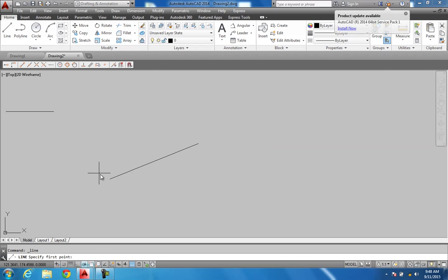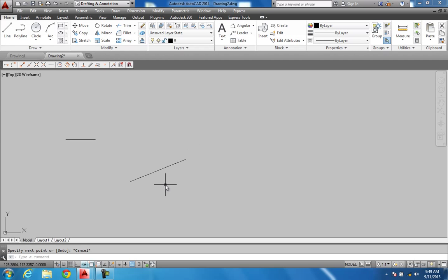And you'll notice here, if I set it on 22, every 22, it'll show up again, like 44, 66, 88, 110. So it'll show up every 22 degrees, and it's really handy to start drawing in angles and things. You can use the polar coordinates, but I like this method too. It's a lot faster in some regards.